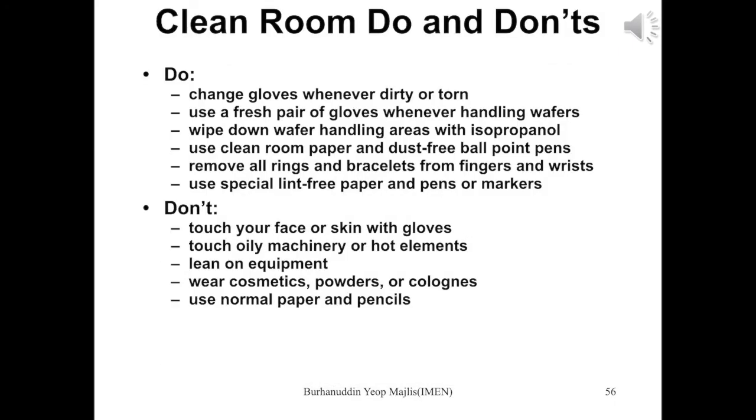Clean room do's and don'ts. This is easy to remember, what we can do and what we cannot do in the clean room. What we can do: we have to change gloves whenever dirty or torn. Use a fresh pair of gloves whenever handling wafers. Wipe down the wafer handling area with isopropanol. Use clean room paper and a dust-free ball pen. Remove all rings and bracelets from fingers and wrists. Use special lint-free papers and pen or marker.